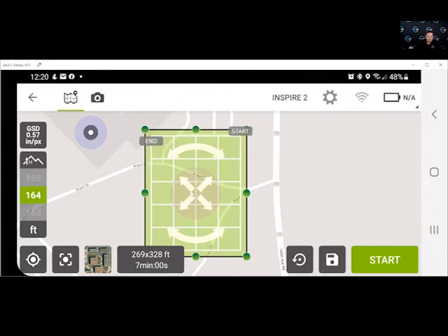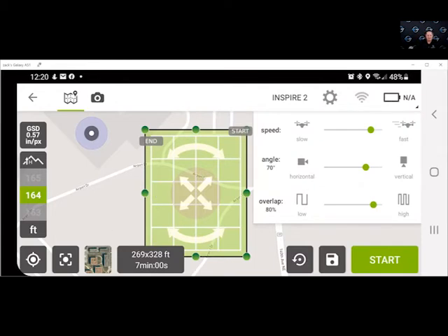They're going to overlap. This pretty much does everything for you. Once you define your area, it tells the aircraft exactly how often it needs to take pictures in order to cover this area. So it makes life really easy. It takes a lot of the guesswork out. We'll be talking about another app a little bit later that is not as convenient with these wide area type projects or the orthomosaic creation type projects, but it's got its own strengths as well. So one of the differences here is the default camera angle. The default camera angle will change to 70% whenever you're working in the double grid. You also lose the ability to face to the center or forward.